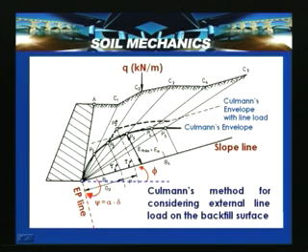So what we need to do is represent this particular wall to a scale, and draw a slope line with an angle phi. Then you need to draw the earth pressure line with an angle psi equal to alpha minus delta from the slope line. Once we draw that, then along the ground surface to A, C1, C2, C3, C4 and C5, we need to draw the lines passing from the heel of the wall to the ground surface. So these are nothing but wedge lines. Possibly one of these lines can become a potential failure surface.